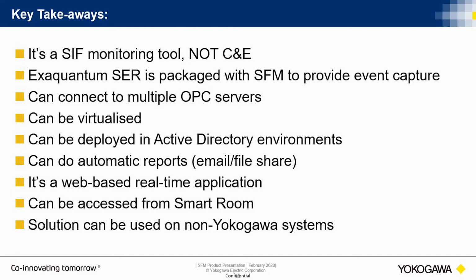It needs SCR, as you saw in the presentation. So it needs a server that has both SCR and SFM to be able to work. You did see that it is capable of connecting to more than one OPC server. So in case, for instance, we have even had cases where the safety events came from a third-party PLC like HIMA. That is also a possibility, but it would take a little bit more work to get those alarm and events into SFM. It can be virtualized, as we just saw, and it can be deployed within the Active Directory environment.